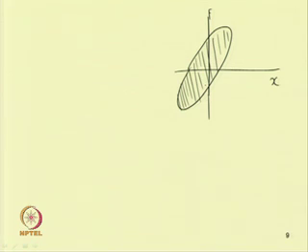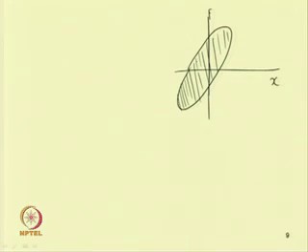This hysteretic damping may be due to the material, since different types of material possess this hysteretic type of damping, and also due to the joints in many structures. So, one can have structural or hysteretic damping also. Hysteretic damping, material damping and structural damping can be combined to have nonlinear damping in the system.